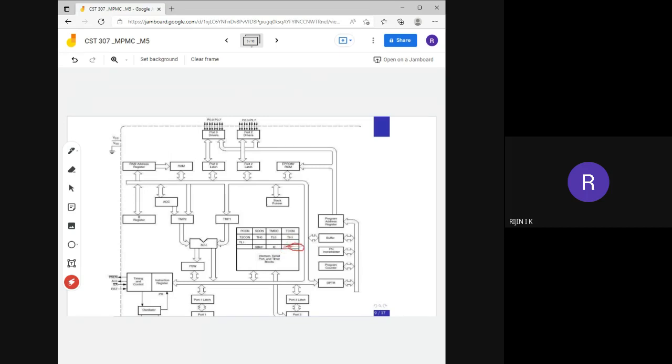Interrupt priority. So all these registers together, we will call it what? Interrupt, serial port and timer blocks. In this block, the PCON register is related to power. SCON register is related to serial communication. Then T mode is related to the mode of the timer. That means for selecting the different modes in a timer, we will use this T mode register.